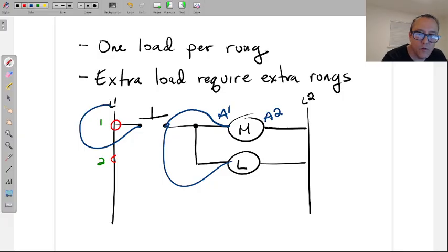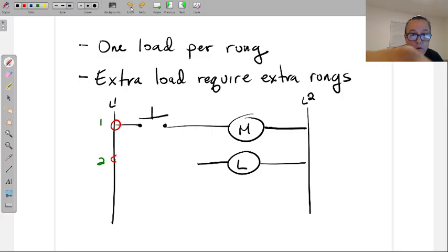And the reason why I don't like the little dot is because I now give the person that's wiring this the opportunity to make that decision as to where to land this wire. And that might not seem like a big deal until you have to troubleshoot this machine later on, and you don't know how they wired it. So now part of you trying to troubleshoot is you tracing down wires. And that is time that you are taking in troubleshooting to trace down a wire where, go back now to how I originally wired this, or designed this.